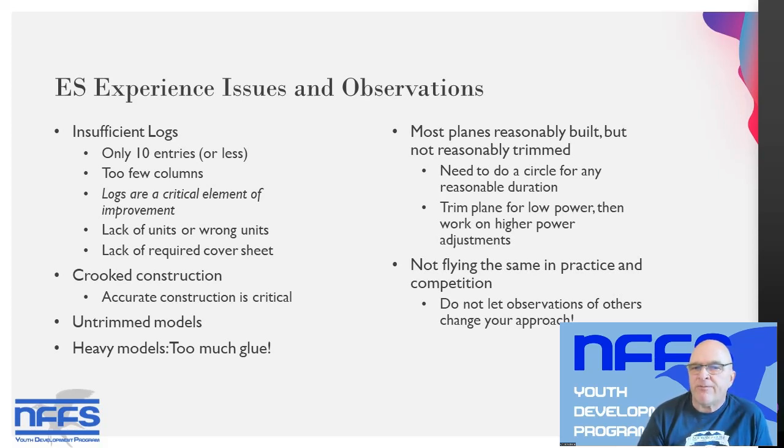You trim the plane for perfect flight at low power and then work on minor adjustments for high power so it properly climbs out. But if it's not trimmed for low power, messing with it at high power is just chasing in circles. It's not going to solve the problem. We'll talk a little more about trim later in the presentation.